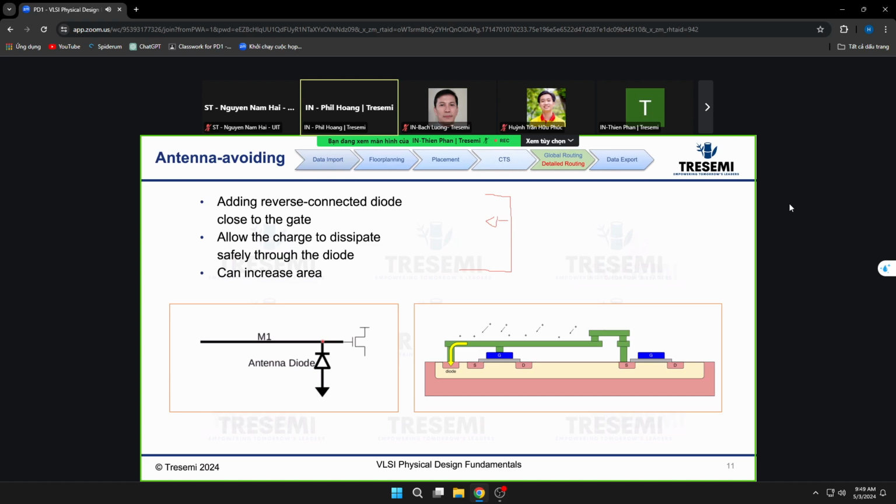Because this is a black box, to be correct by design, you can insert a diode at every input of the analog blocks. So you don't have to worry about all these wires, because the diode will collect the charge. In case you have a black box. Just some note.